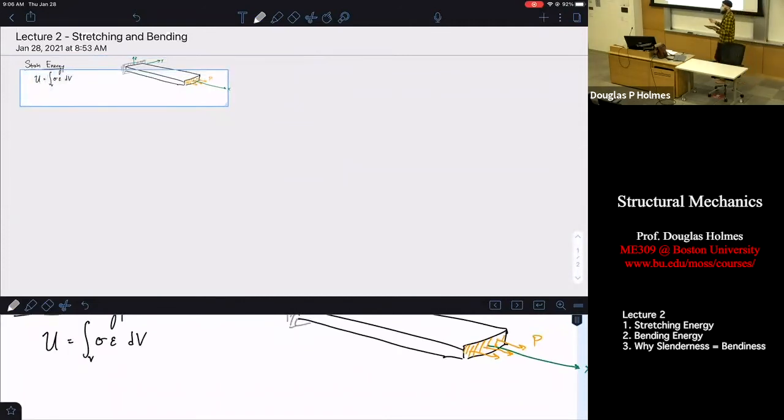There are two ways you can do this, and it's important if you ever go into experimental mechanics, any sort of structural mechanics or experiments on materials or structures, in lab or in a computer simulation. You often have two choices, and they seem like they're going to lead to the same types of behavior, but it's not always exactly the same. The choices are, you could impose a known amount of force and measure the strain. That's what's called load controlled or force controlled.